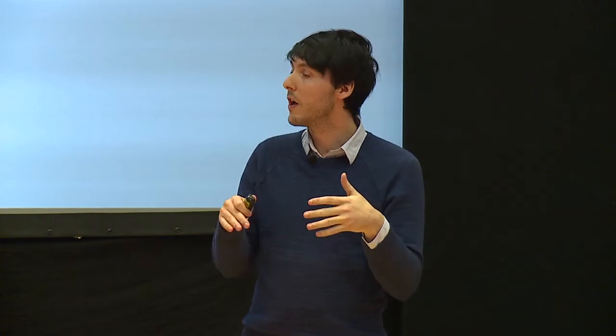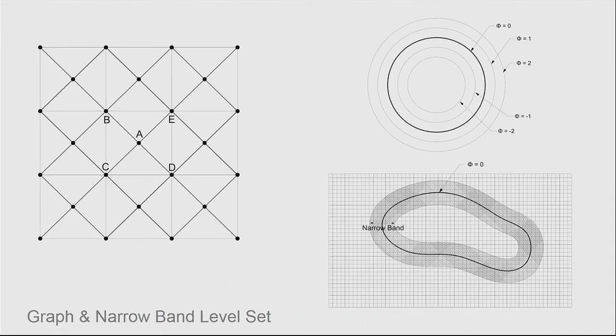And so taking that approach of parametric and generative, I'm going to talk a little bit more now about how Element, the program that we've done, represents geometry. Because you need a way of representing geometry to actually play these things out. Otherwise, it's just abstract, right? And so our key two ways of representing structures, different than the traditional way, are through a graph and then a volumetric representation, which is a narrowband level set.